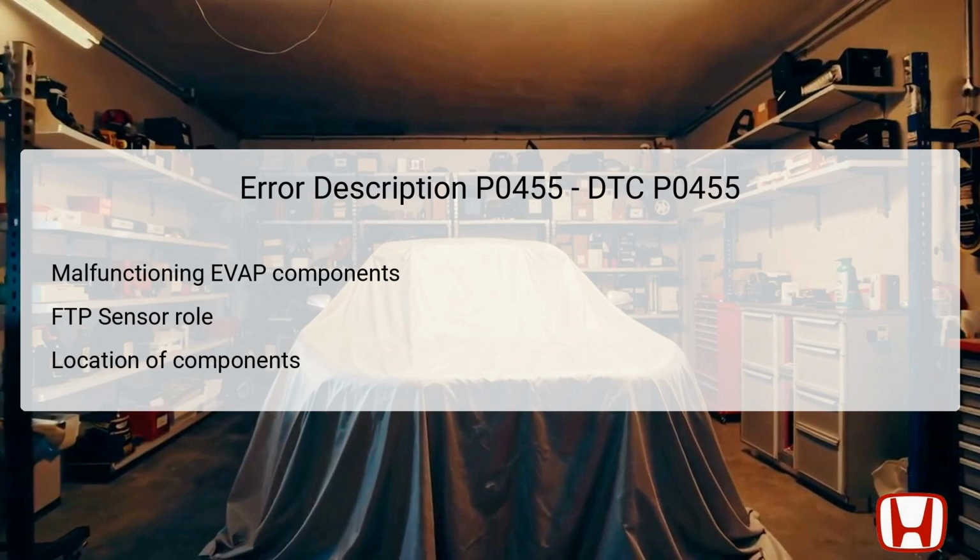The P0455 error pertains to a malfunction in the EVAP system, specifically where there's a significant leak detected. Key components involved include the EVAP canister, which captures fuel vapors, the EVAP canister purge valve, which controls vapor flow to the engine for combustion, and the FTP sensor, which measures the pressure in the fuel tank.